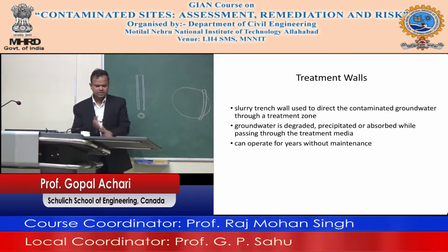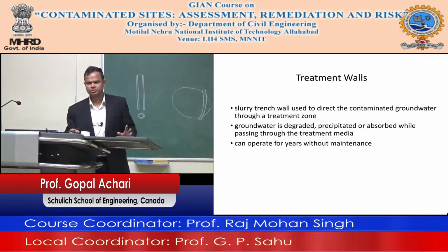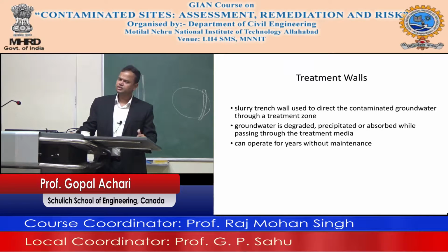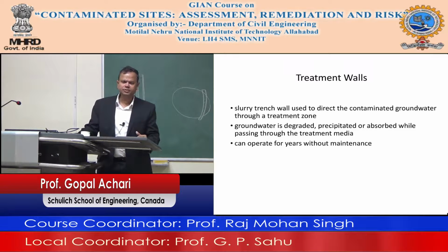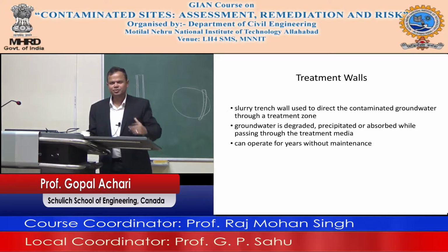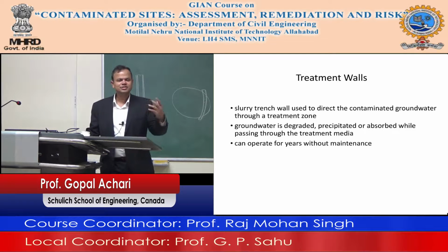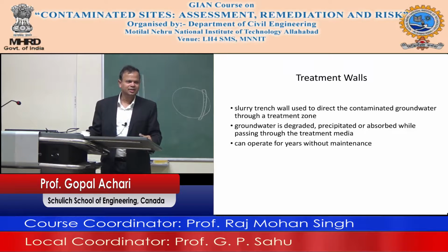So some of you are doing contaminant transport models, right? This is something to think about. The purpose of a model is to develop the model, but you can also look at, okay, if I put a treatment around it, how will my plume shrink? How will my plume change? The beauty of a model is that you can play it on a computer system and see different scenarios without actually trying it in the field.